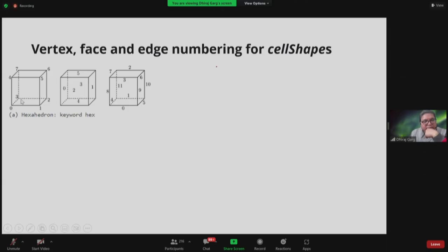Then back to 3, which is in the negative x direction, and from 3 it will automatically come back to 0. If you look in the positive z direction, this is counterclockwise, because the angle theta is positive in counterclockwise. Hence it creates this face whose normal is in the positive z direction. Now, to create this side, we define 4 in the positive z direction, and from here again you follow the same sequence: 5, 6, and 7.